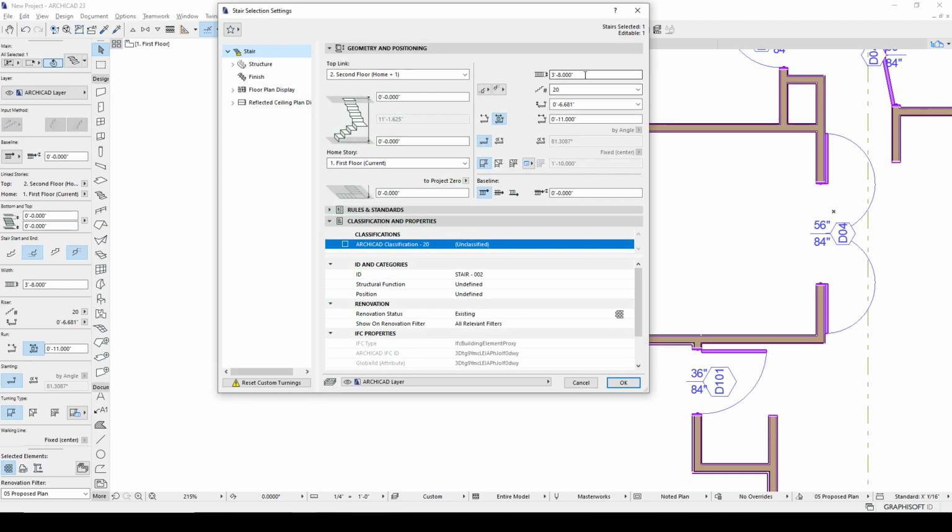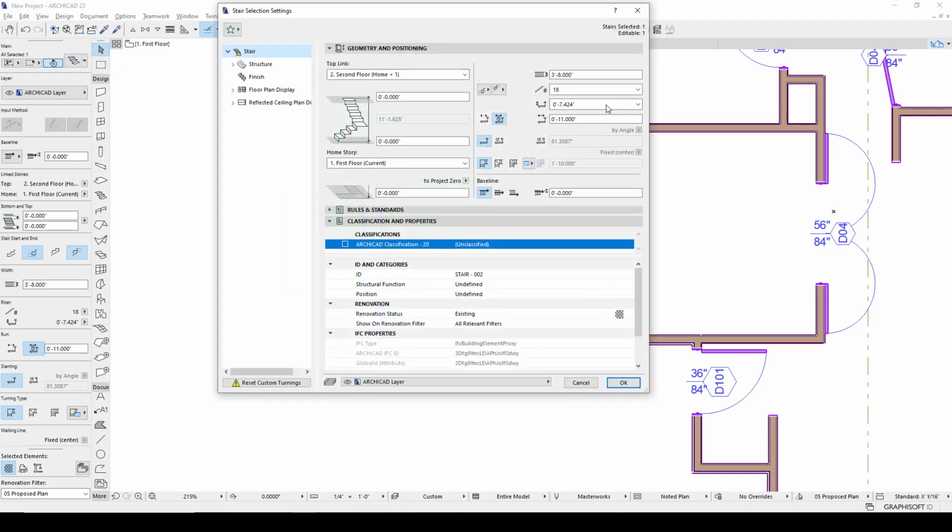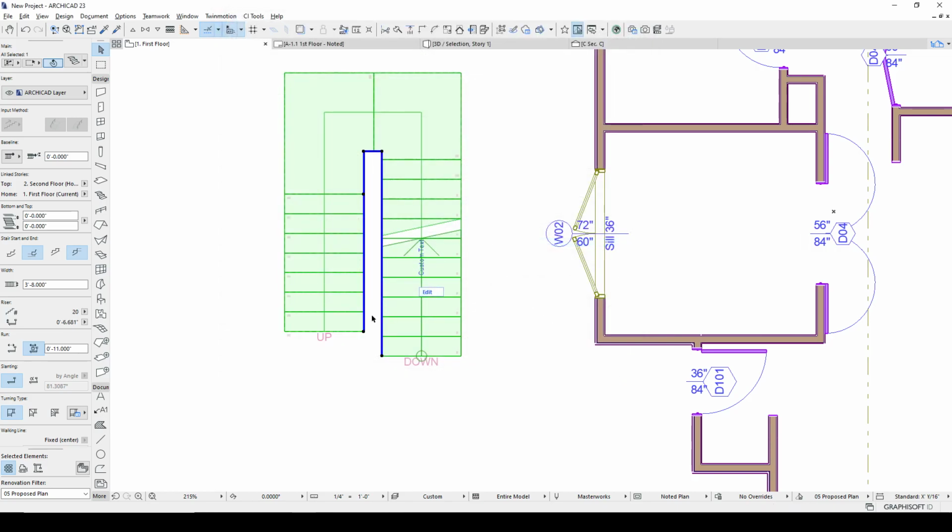So now if we go back in here, we can see, okay, 3'8". This is the number of treads. These are some different options. When I did that, it removed a couple treads because these are the options that exist between the max and the min that I offered it. And I go, let's do this tread here. And boom, it adds the steps. I can hit here. I can add, subtract.